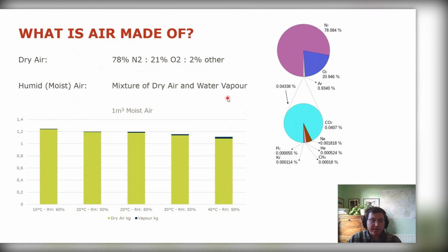The thing about them, as far as we're concerned from the point of view of designing ventilation systems, is that all those gases are perfectly mixed, and we can deal with them as a mixture. We can work out their properties once, in terms of things like specific heat capacities and densities, and we don't really need to be recalculating the state because the percentages don't change and the behavior can be modeled as a perfect mixture. For all intents and purposes, if we only dealt with dry air, we wouldn't need to worry about what exactly it is made up of.